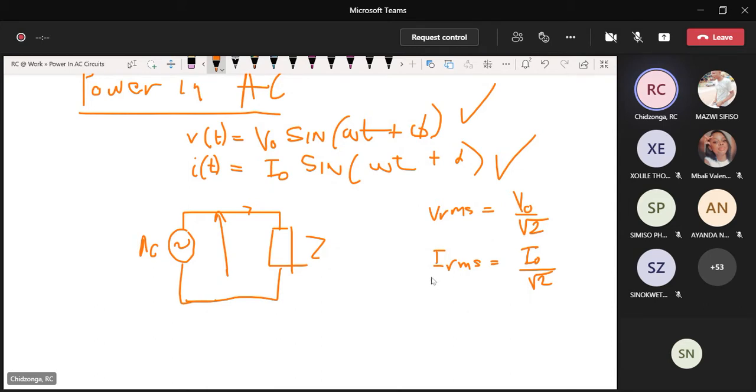So when you hear 220 volts, 400 volts, those voltages are actually root mean square values. But in normal talk or normal application, people don't say 220 root mean square voltage. They'll just say 220 volts. So it's implied that it is a root mean square quantity. The root mean square quantity is that magnitude of an AC voltage that will give the same power as a DC source of the same magnitude.